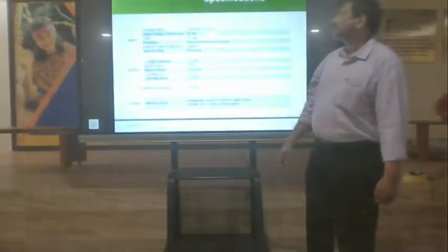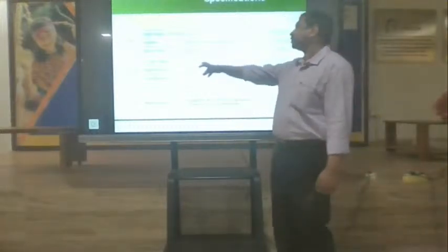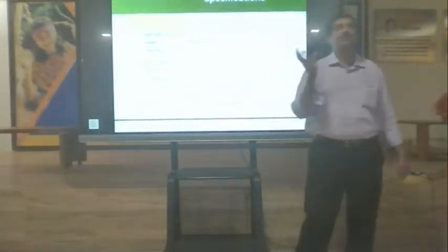Then the startup time. The time required to attain the maximum, that is the specified output, is 30 milliseconds. Those are all the input specifications. Similarly, you have the output. What is voltage tolerance? It is the variation. Say if my output is 5 volts, then how much variation is allowed?